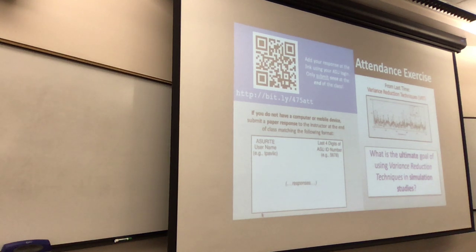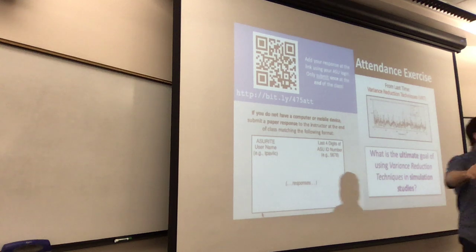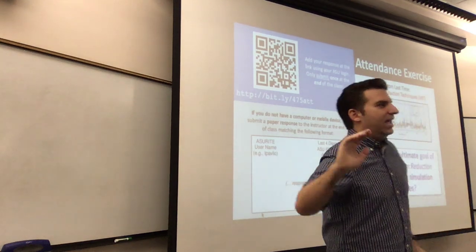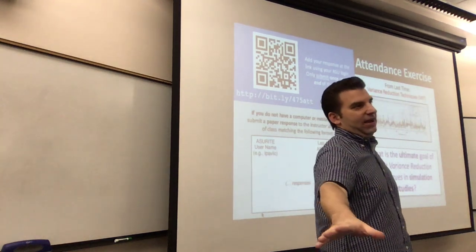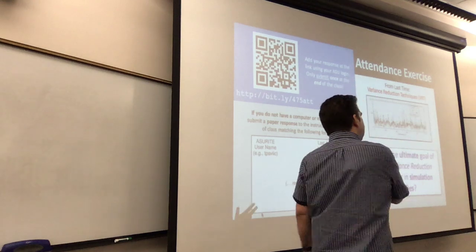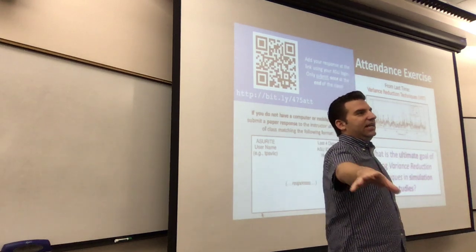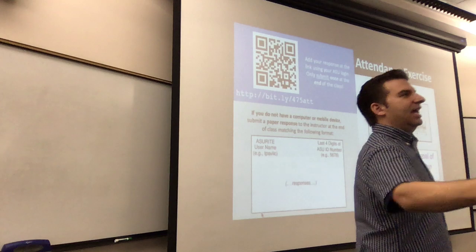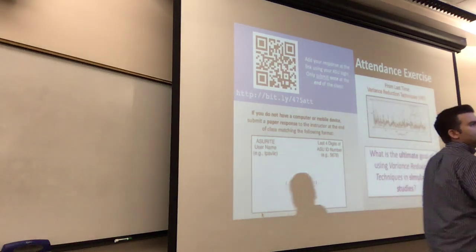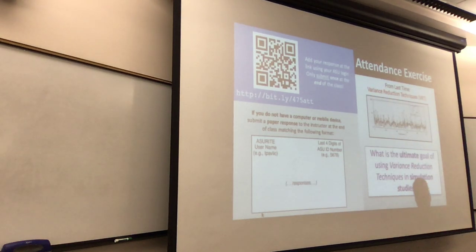Yeah, the number of replications, that's right. The major point here is that we do want to reduce our confidence interval size. That's the ultimate point. But we either have to pay for it by spending an hour on a sim instead of a half hour, or, if we design the experiment right, we can stick with a half-hour simulation and get narrower confidence intervals. So it's to reduce the computation time.